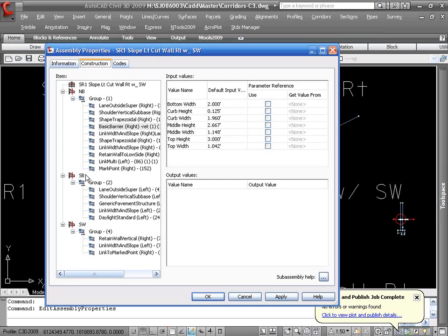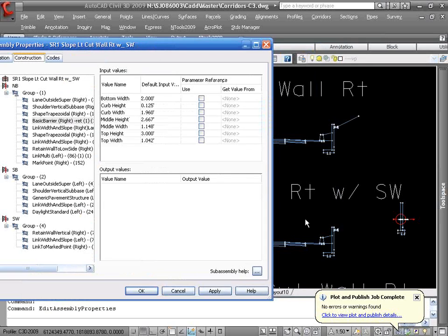And in this one that came up was that this sound wall here has a link to marked point. That's the way the sound wall has basically the elevation is controlled by the OG. Whereas the pavement, let's see if we can make you see it in here. There we go. Whereas this wall has a height that's sort of independent, and then it's supposed to have the slope in between the two of these. So there's a marked point on this sort of channel behind the wall, and this link to marked point that goes to that.